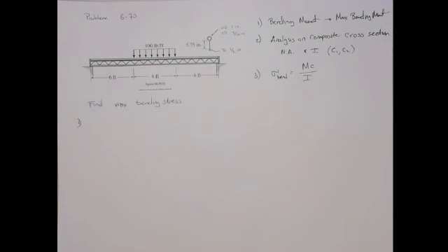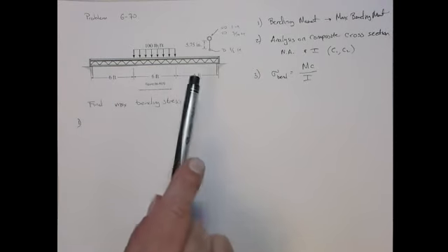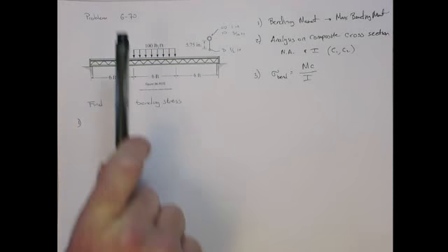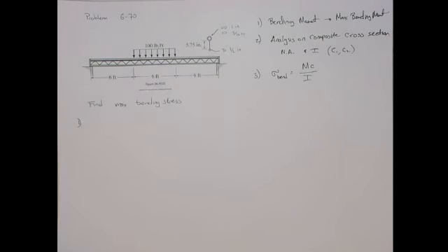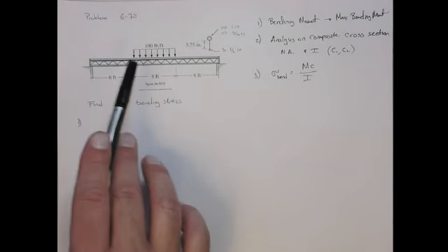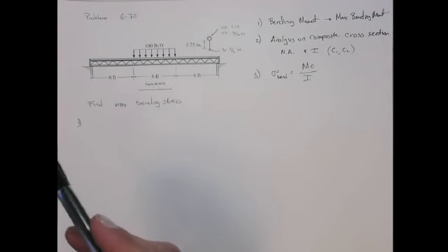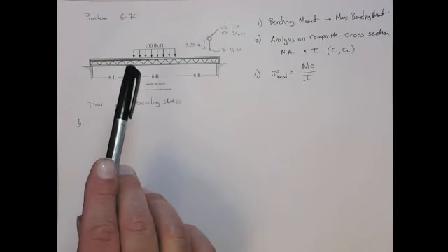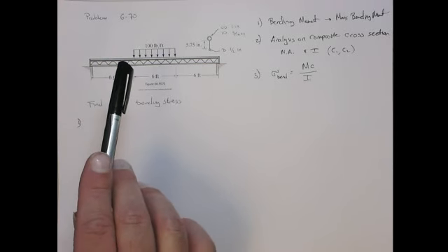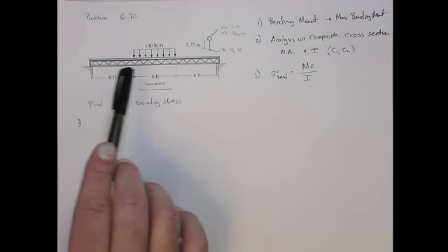So let's do the bending moment diagram first. Again, you need to figure out where the maximum bending moment is. The cross-section is uniform, so wherever the max bending moment is, that's the section where you'll have the maximum stress. If you had a beam where the cross-section or materials changed, you would have to check for the max stress in each of those sections, so you'd have to look for the max moment in each one.